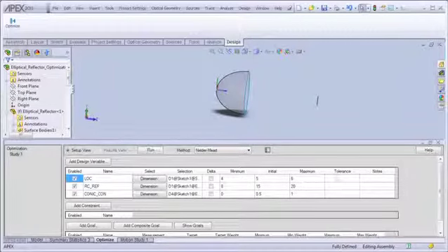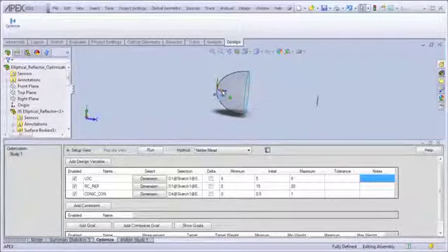The tolerance in this particular case is a computational and not true manufacturing tolerance of the variable. Variables are changed by various amounts during optimization in order to find the best solution. The optimization algorithm will limit the amount of variable change to the tolerance amount when an optimization step or an estimate of the optimum attempts to change that variable by less than the specified tolerance value. You can additionally add notes in this field to give further information about the description of the variable that's used in the optimization. In this particular example, we have as variables the location of a source in the reflector, the radius of curvature of the elliptical shape, and the conic constant of the elliptical shape.